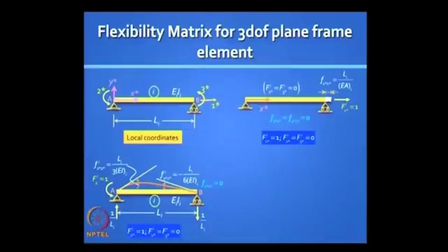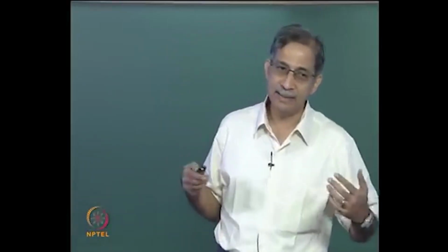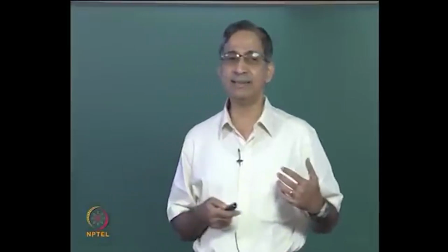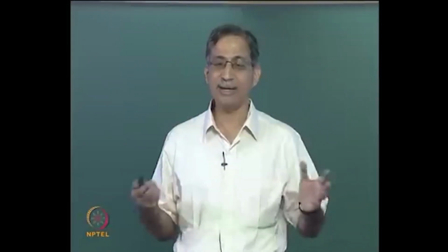You do not have any axial change in length, that is an assumption we are making, because we are saying that the flexibilities do not interact, the axial degree of freedom and the flexural degrees of freedom are independent.